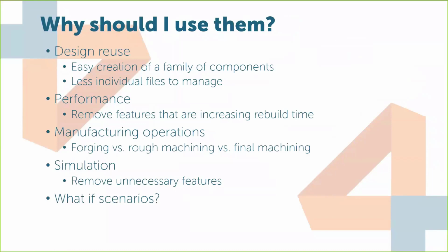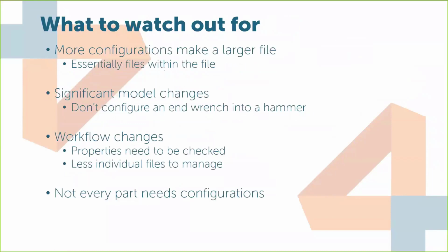And the example that I'm going to show here today is what-if scenarios. I just want to try a couple things out. I'm going to use some configurations to see if they work, and if they don't work, delete the configuration. But if they do work, then I can easily leverage that configuration. It works out nicely for assemblies because I don't have to swap parts in and out of an assembly. I don't have to worry about, if the part's too drastic, maybe some mates are broken. It's the same part, just switching configurations. Things tend to rebuild and update nicely in stride with that.